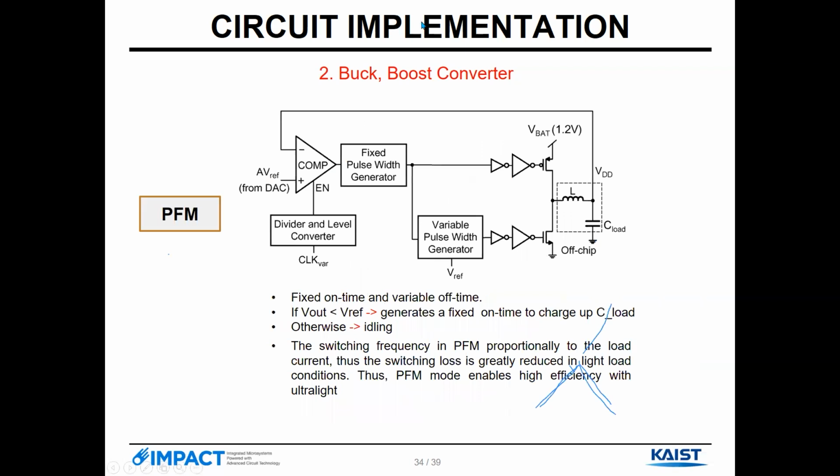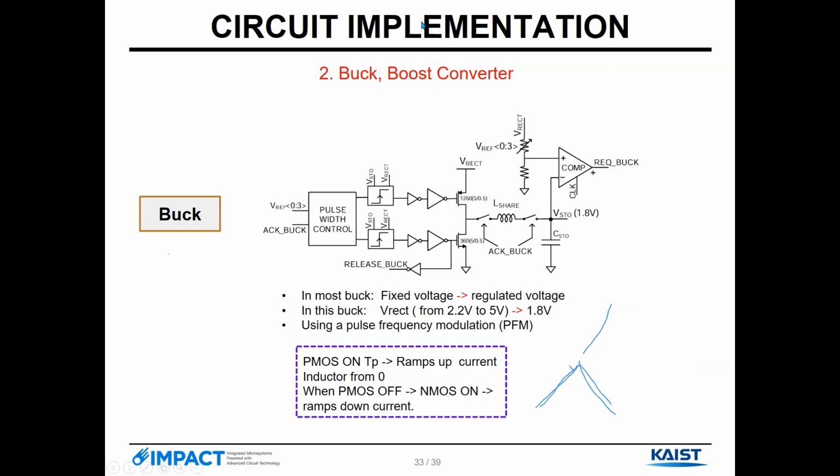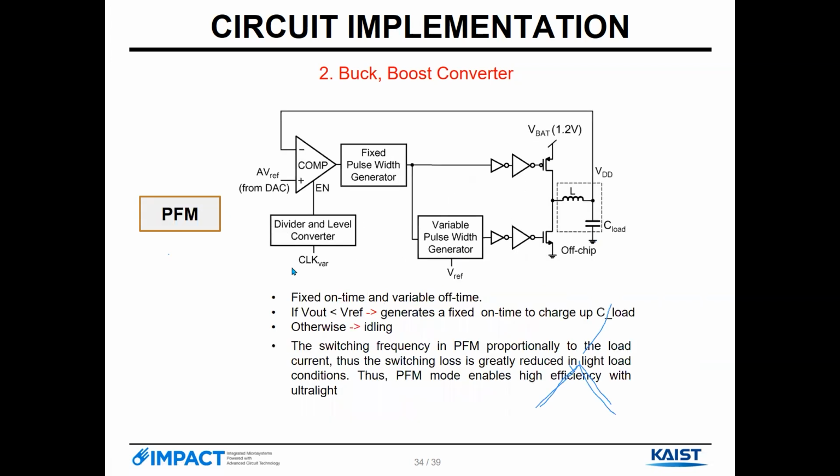That is what I said about pulse frequency modulation. It's usually a fixed on time for the P and a variable on time. In the P mode we use the fixed on time, and in the N mode we use variable on time. We measure the output voltage and compare it with the V reference.